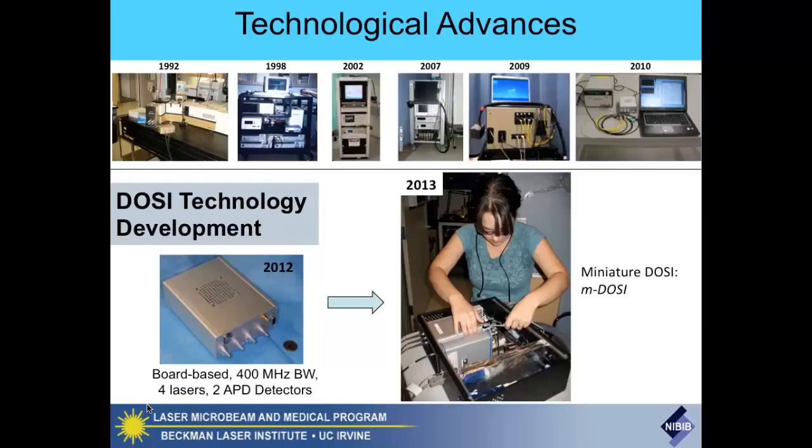And you'll see this in the lab this afternoon, that the technology, I started working on it in the early 90s, and it took up an entire room. And as all good things in our field go, they get smaller and less expensive. So here's the refrigerator size instrument, which you'll see. And here's the external hard drive size device that has 4 laser diodes in it and a board for driving the sources, and the APD is inside of this box, APD avalanche photodiode detector.